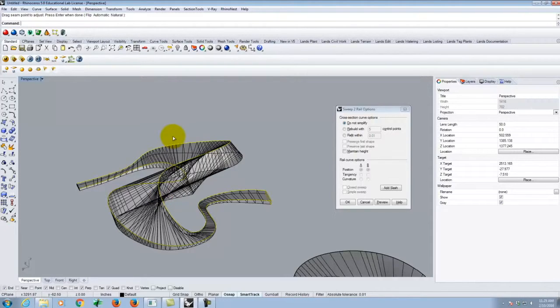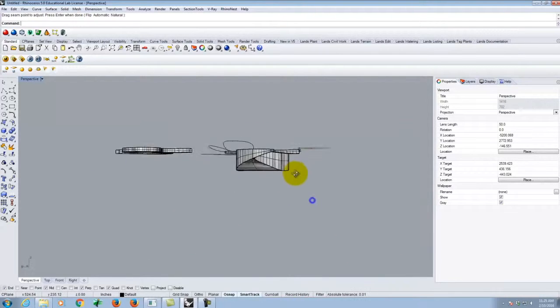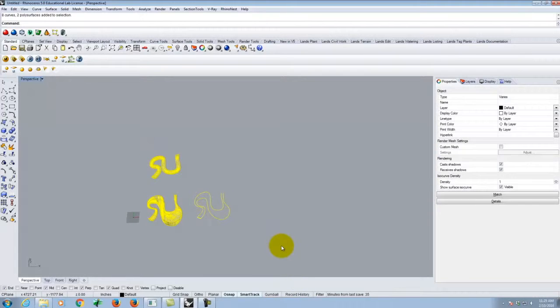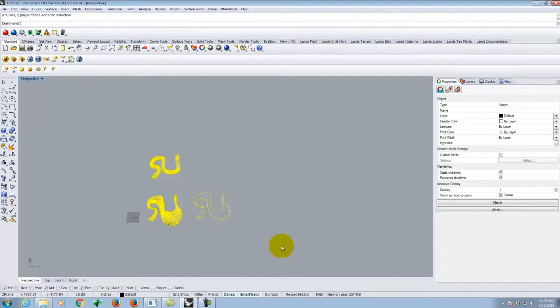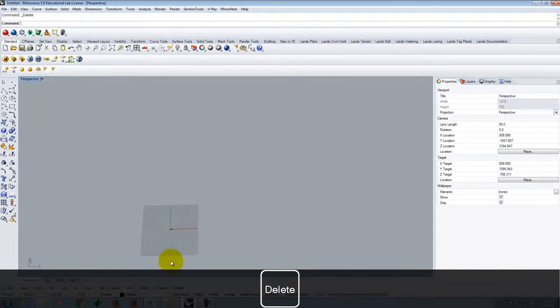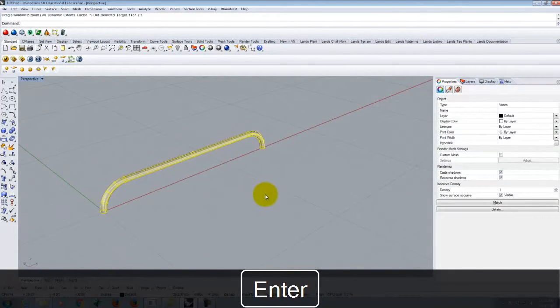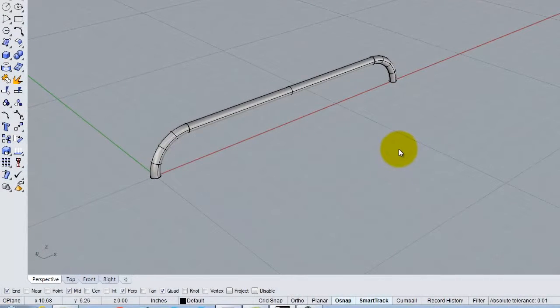So if you were doing an actual road going up a piece of topography, you may draw the road width and project it down on the piece of topography, and then you could do a sweep through those two. Maybe an option. Anyway, I know all of this was completely tangent to what we're trying to do, but I think it's important to explain what sweeps can do and can be beneficial for. So let's come all the way back to our very simple object right there, and we're going to continue working with this object, and we're going to build a few more pieces with this.